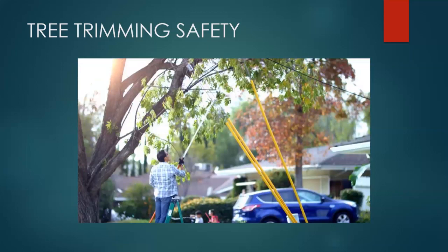When an unqualified person is working on the ground in the vicinity of overhead lines, the person may not bring any conductive object closer to unguarded, energized overhead lines than the distances given in the previous slide. For voltages normally encountered with overhead power lines, objects which do not have an insulating rating for the voltage involved are considered to be conductive.